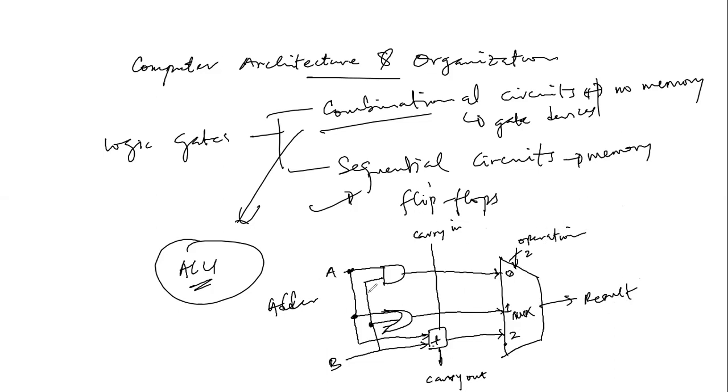So looking at this, we know that your multiplexer is strictly a combinational circuit. Your adder is strictly a combinational circuit. Then the gate devices, your AND gate, OR gate, NOT gate, they are all combinational circuit devices. So we know that if you want to design a computing system, the arithmetic logic unit of that computing device will be designed and fabricated physically, in terms of the hardware implementation, using combinational circuits. I think that's where I'm going to, okay?